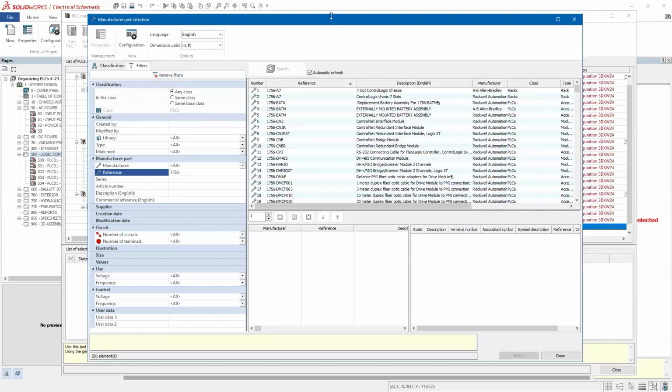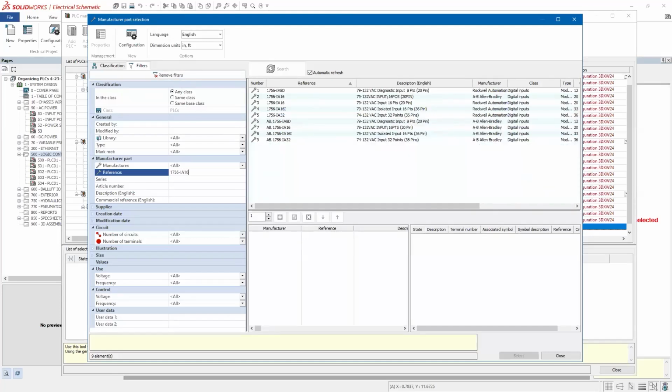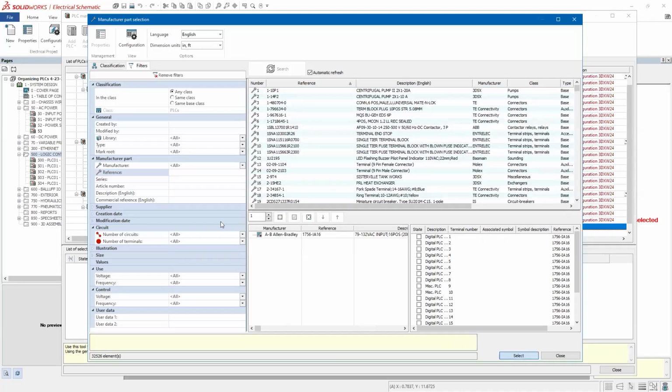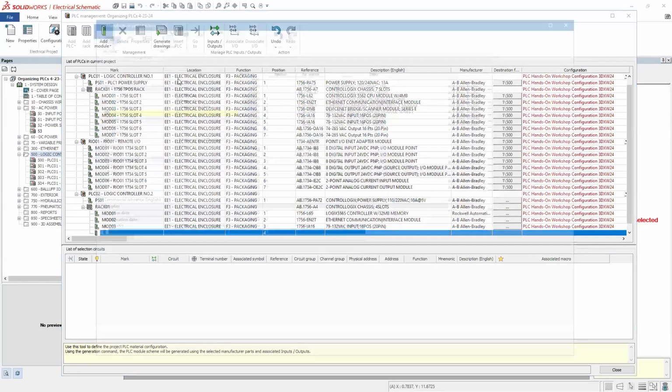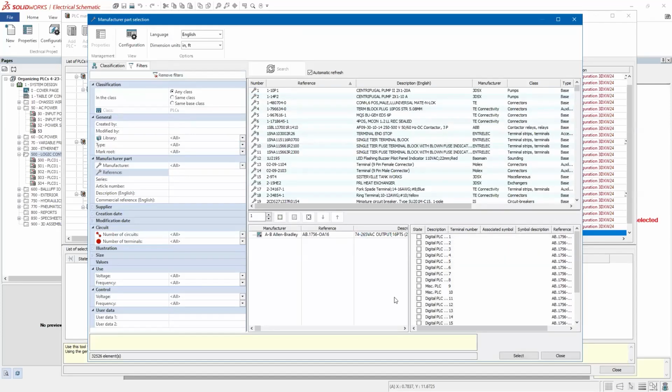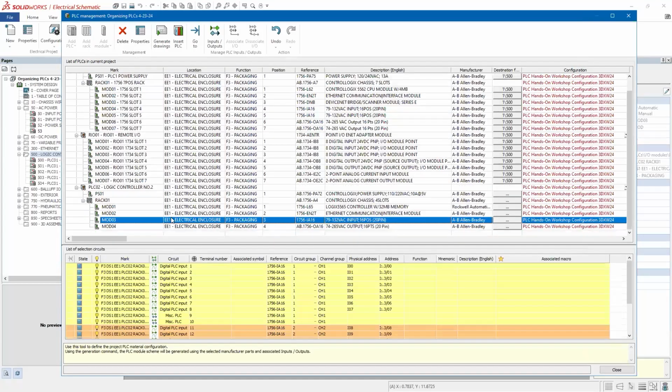We had one question come in about the IO link blocks, basically the modular blocks that are mounted or connected via DIN cables that work as breakouts for the IOs. Those can be handled in several different ways. You can keep them as a PLC if you wanted to. You could create them as a connector. You can have them just as a general component, and there are several different ways of displaying those in your schematics. Cool, thank you.